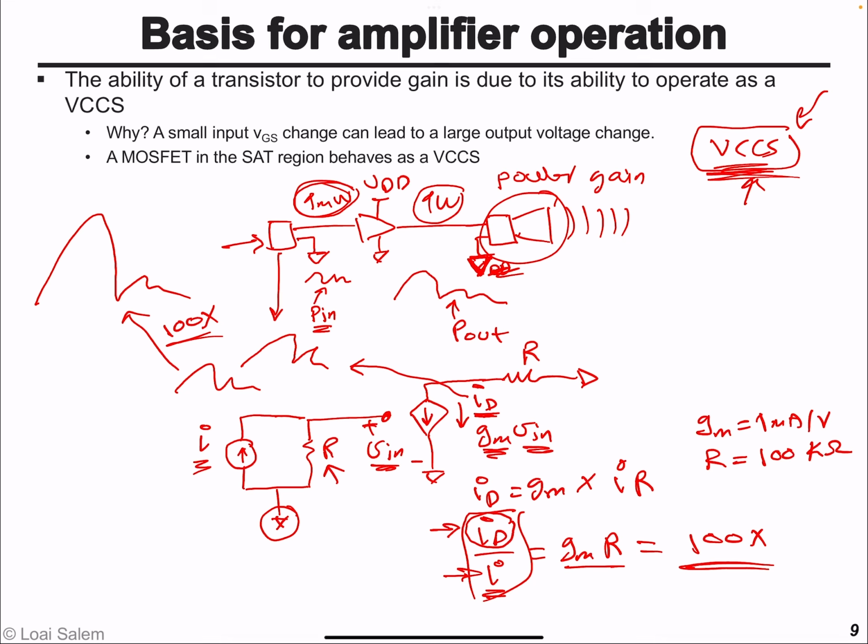So essentially the power produced in the speaker, the speaker being represented just by a resistor, the output power P out, will be the current produced by the voltage controlled current source squared times the equivalent resistance of the loudspeaker. And here I'm assuming that the equivalent resistance of the loudspeaker is equal to the equivalent output resistance of the microphone model, just for simplicity.